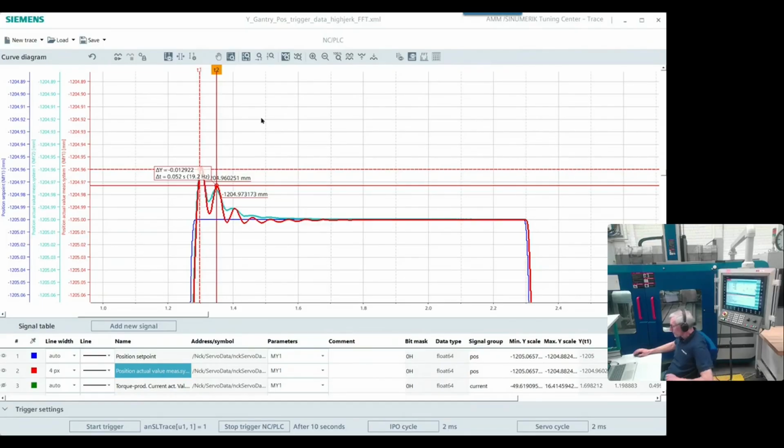And there's also one, not only one. There are several use cases using the math here. Some easy use cases are if you want to transform some units. Let's say you have only recorded the motor speed, but actually you want to know about the axis velocity. Then you need to get the numbers from the gear ratio and from the lead screw pitch, and then you can transform the signal from the drive into the signal of the axis.